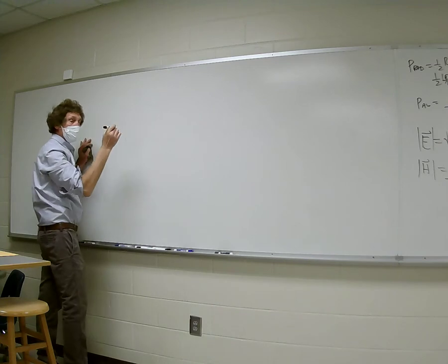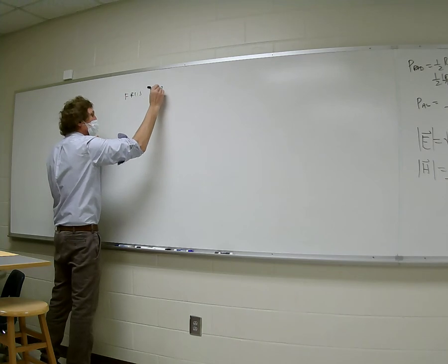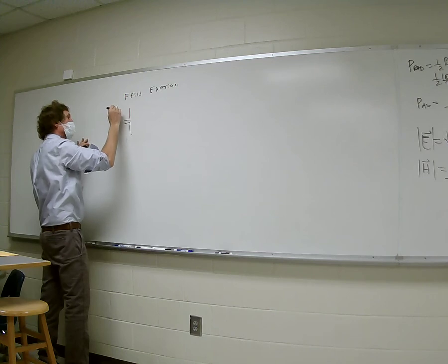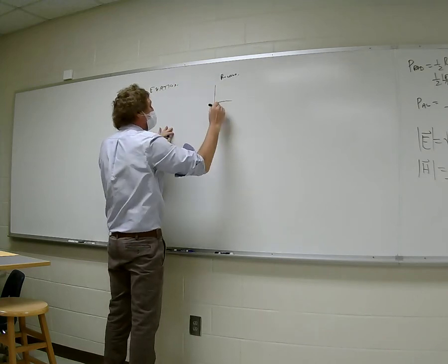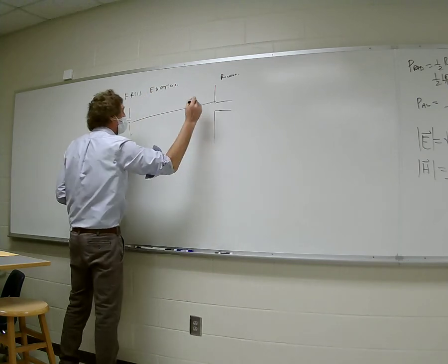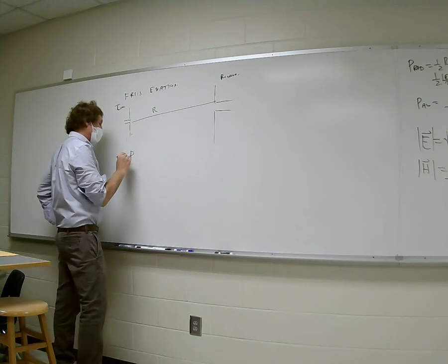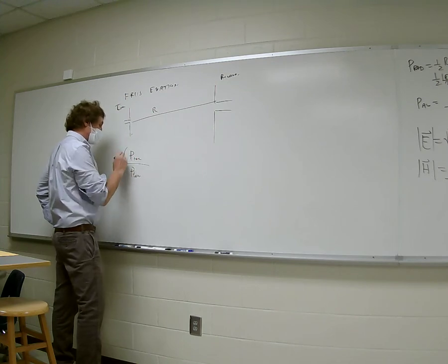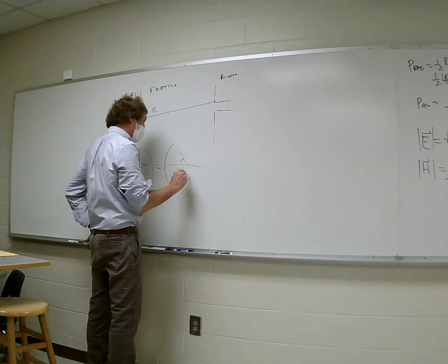So now if we take a look at this, this is the actual Friis equation. It says if you have two antennas, I'll call this transmitter and this receiver. You have a distance r between them. Then you can say the power received divided by the power transmitted or radiated, this ratio would be equal to lambda over 4 pi r squared.